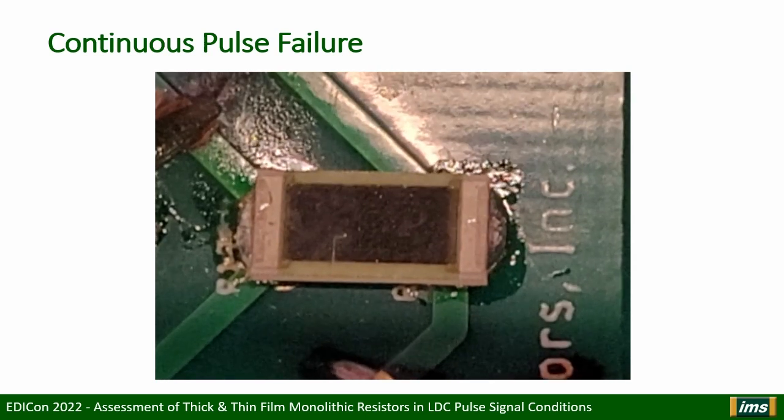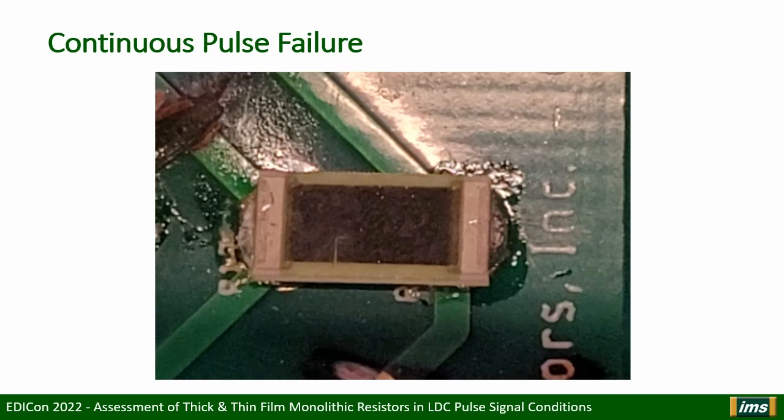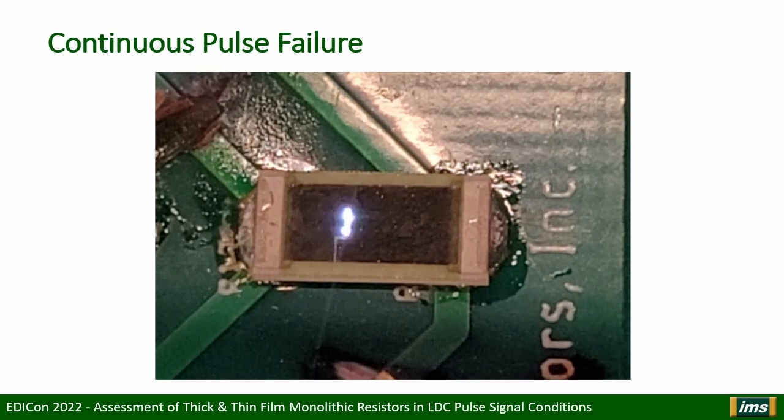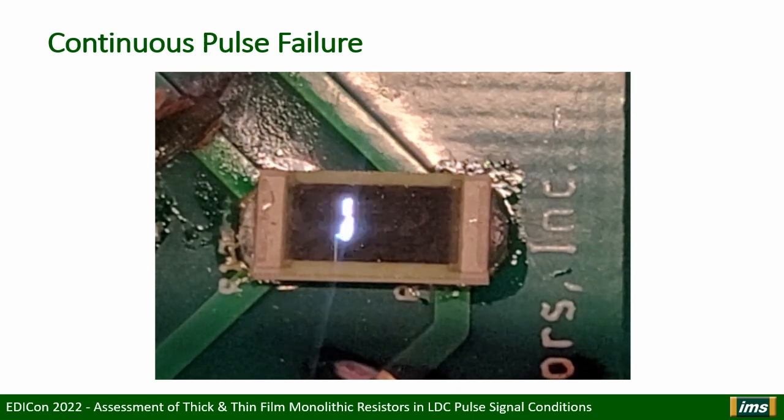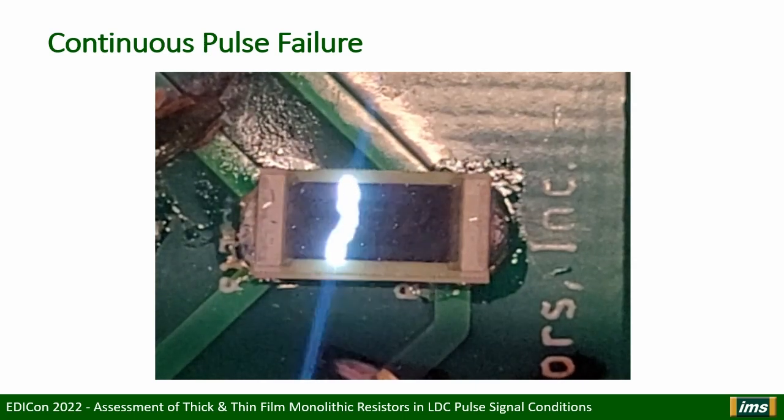Now there's material missing, and on the next pulse, the choke point has an even smaller CSA, causing the next micro region to fail. As you can see, this occurs successively and quite rapidly under the conditions customers can use. Below the critical value of resistance based on case size, it's entirely possible to make a part fail cold with no appreciable temperature rise.